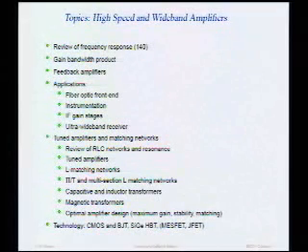Now, silicon germanium bipolar is a lot like standard bipolar that you guys know and hopefully love, but silicon germanium transistors are actually HBTs. They're heterojunction bipolar transistors, which means that, from your perspective, the small signal model looks the same. The only difference is that RB is smaller and FT is higher, so it's nicer.